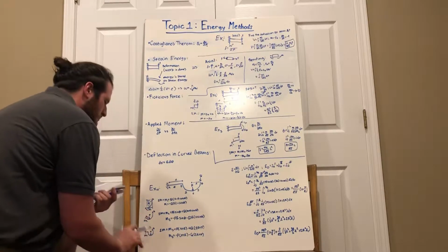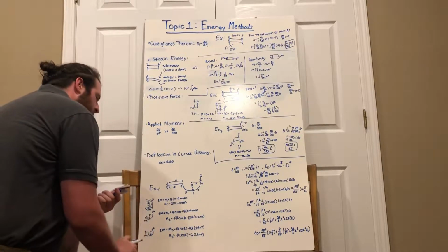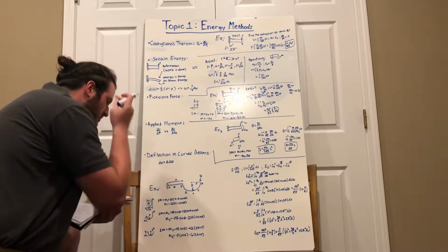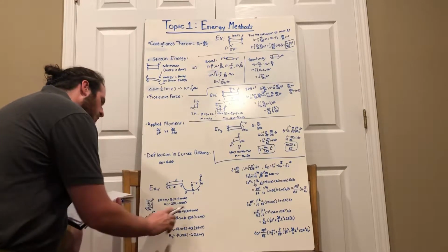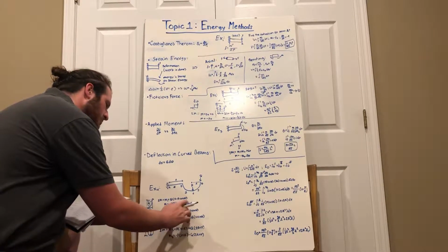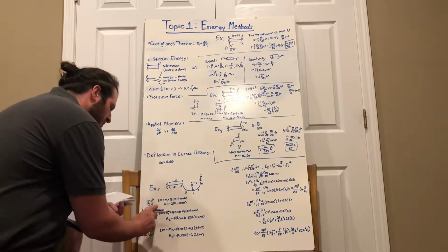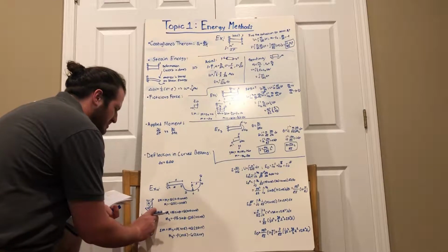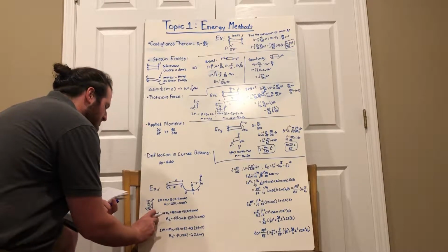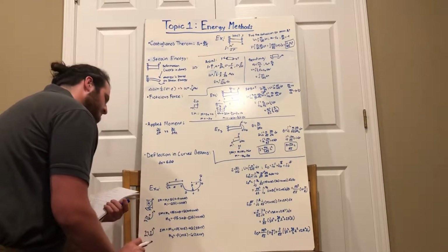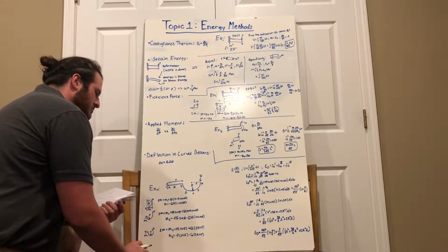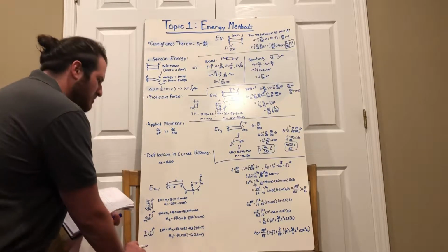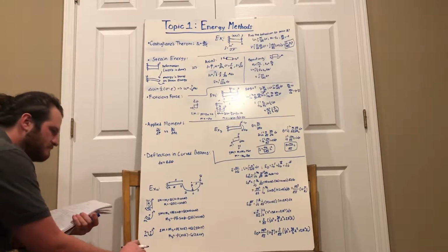Theta. Sine theta. That'll give us our perpendicular distance to the force, plus QR plus r sine theta. Here it's a similar process, except for flipping it to sine instead of cosine to get this matching angle. And we're adding r instead of subtracting because we already have this radius. Rearranging, we'll get M2 equals negative PR sine theta minus QR times 1 plus sine theta.